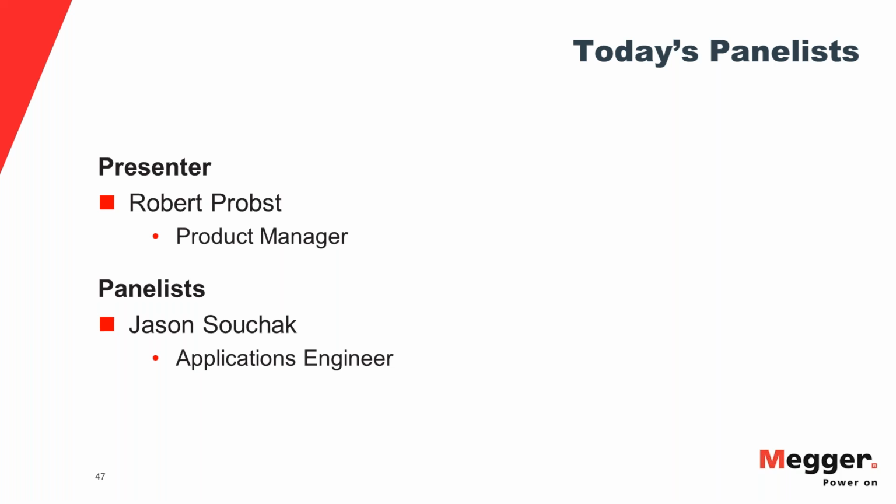Okay. The next question is, someone noticed the testing time is 30 minutes in the IEEE guide. Does that fall into this category of compromising test times? Okay, this is a little bit of a convoluted issue. First of all, you have to be careful what you're talking about, acceptance testing or maintenance testing. So for maintenance testing, they say 30 to 60 minutes, with recommendations for 30. IEC is just strict. They say 60 minutes on service aged cables.